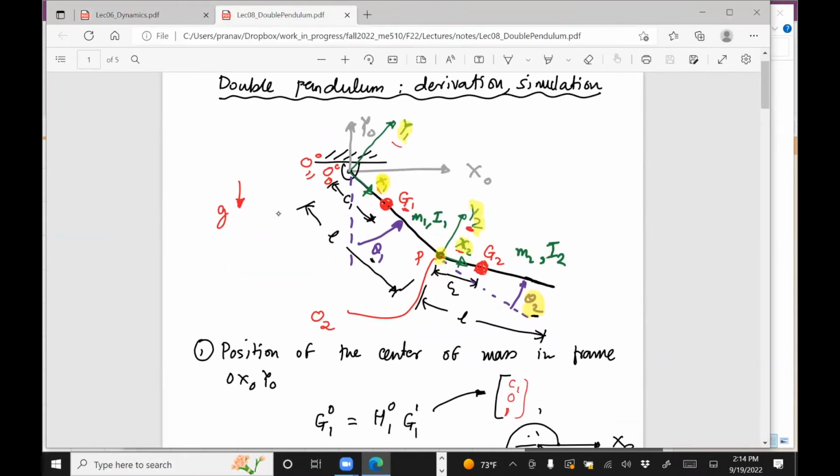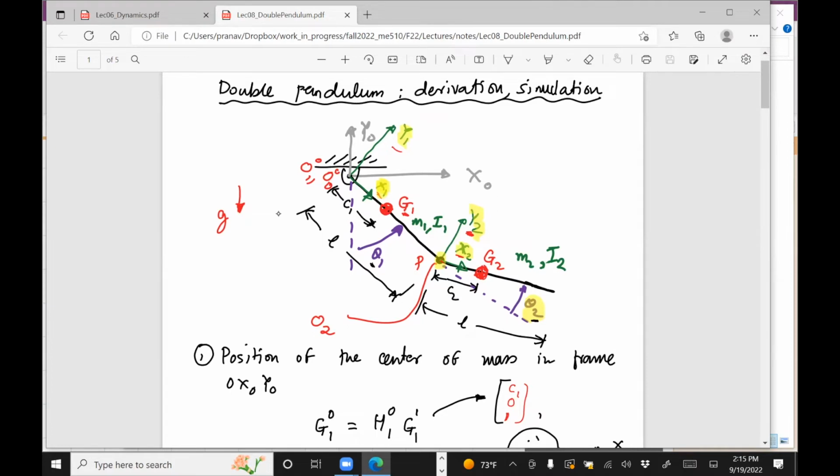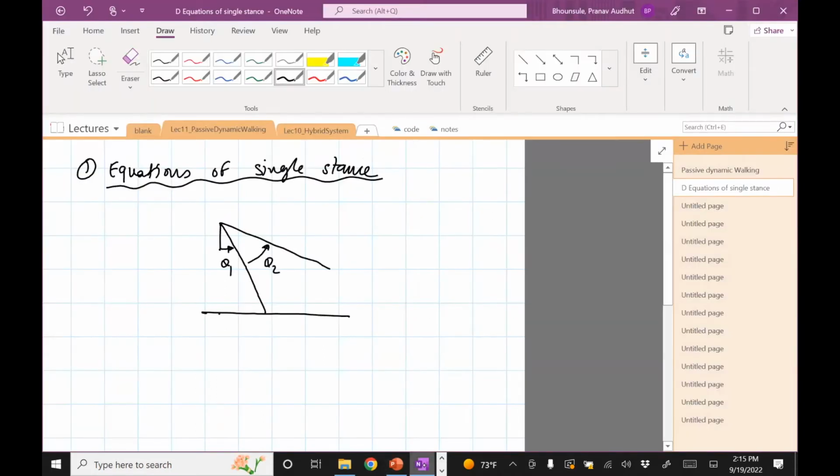Okay, so this is how a double pendulum looks, and the way I've defined the angles is, it's basically the angle between this leg and then this one. Can you see my cursor here? So it's this angle, θ2, right? I chose that because that was the most straightforward way for me to write the equations. But in this case, I'm trying to make it more convenient for myself to do control later on. And so what I do is I just choose it to be the way it is. And then we'll figure out what the right angle is when we use our frames to take care of the fact that it is not the straightforward angles we wrote down for the double pendulum.